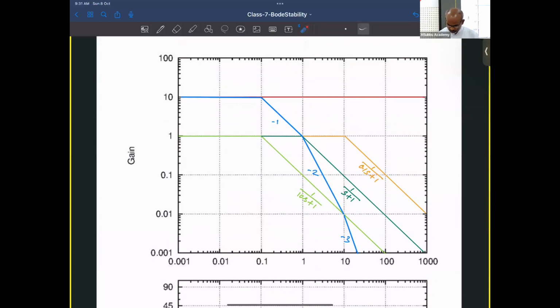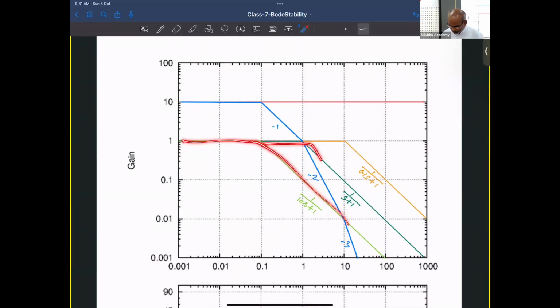Before going to that, we can construct the Bode asymptotic lines for every system. The total is simply, till the point of 0.1, there is no change of slope. We have this blue line representing the total, so this has a slope of 0. And from then, here we have a slope of -1. So from then we have to start another line, which is drawn so as to have a slope of -1. So -1 is simply a negative slope.